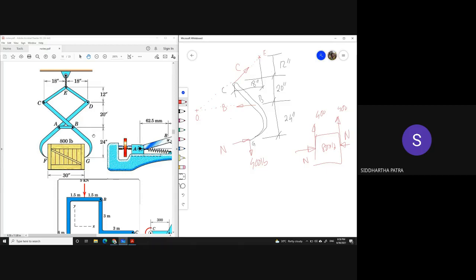Now I showed two aspects of why there should be a normal force. First of all, there cannot be a friction force without which you can grip an object. You cannot grip an object. That is a physical aspect. The mathematical aspect is there has to be one additional variable, otherwise the system is rendered inconsistent: two unknowns and three equations of equilibrium for this rigid body. And why does that physical aspect and the mathematical aspect coincide? It's because you are only being presented with optimally constrained problems.